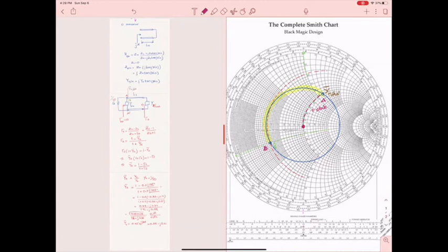So I consider the transistor as my load. Since they gave me the reflection, practically I know its input impedance, Z sub S, and that is my load. And since I know that at the end I'm going to have a 50 ohm load, which could be my source, ideally, I know that I have to match to 50 ohms, which is the resistor at the end on the left. And that's why I did it. Okay, and that's where you got gamma A A prime equals 0, and that was your target. Uh-huh. Okay, great.